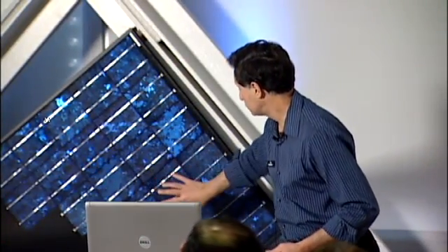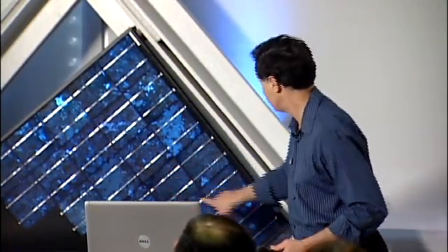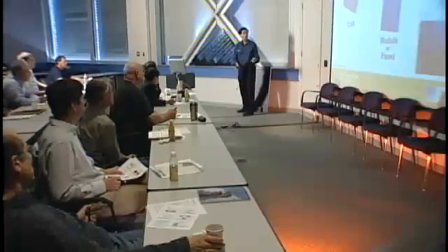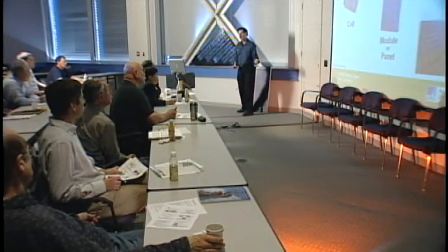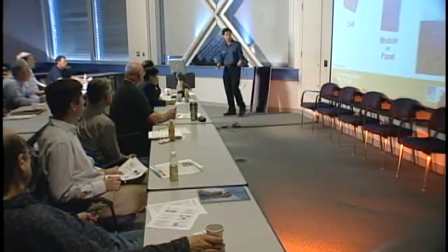A cell is one of these pieces here. It's a small unit of this transistor-like material wired together in a certain way to produce about half a volt. These are hooked together in whatever size to be a module or a panel. Those terms are sort of used interchangeably. And then you hook as many of these modules together as you need for your array. So it is a very modular and very adaptable technology. You can make it whatever size you want.